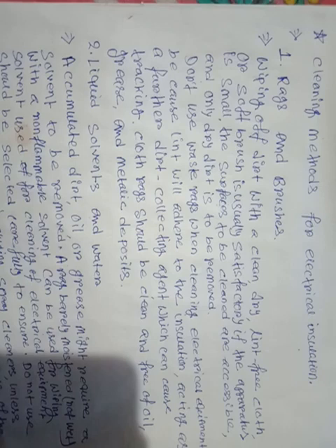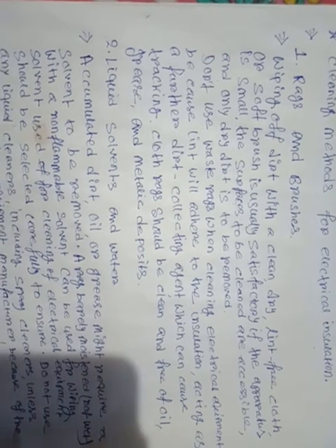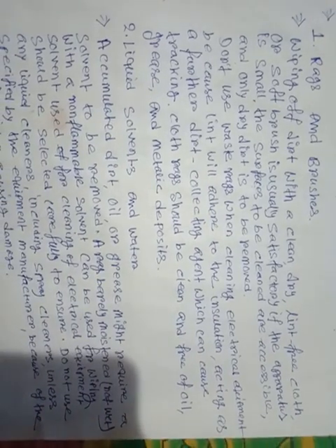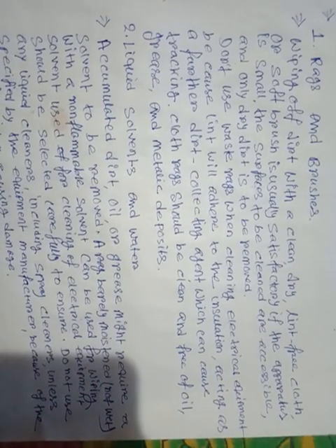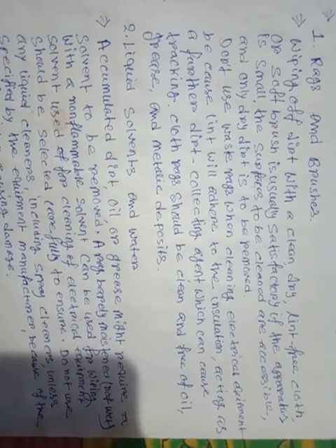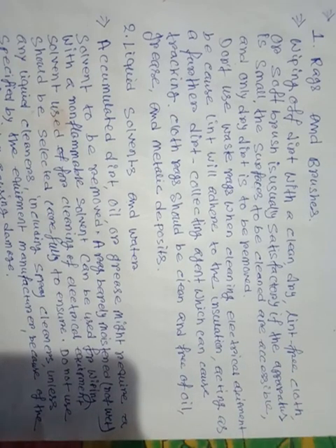Second is liquid solvent and water. Accumulated dirt, oil, or grease might require a solvent to be removed. A rag moistened with a non-flammable solvent can be used for the wiping. The solvent used for the cleaning of electrical equipment should be selected carefully.